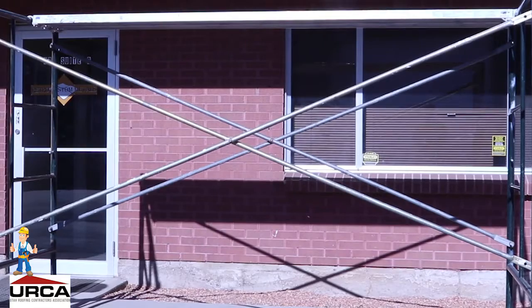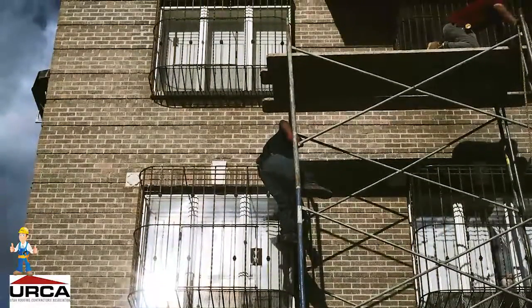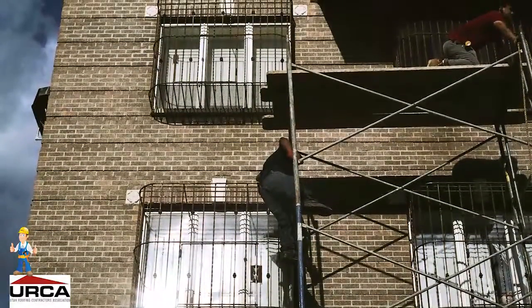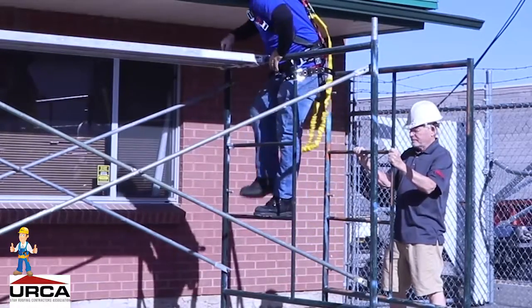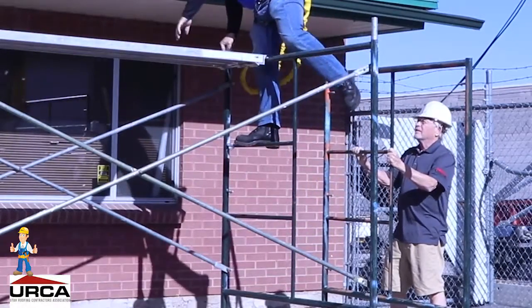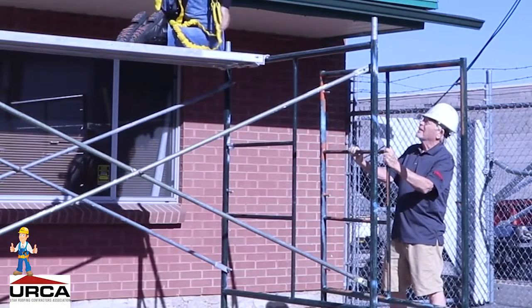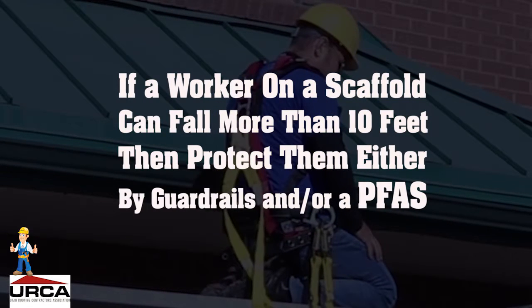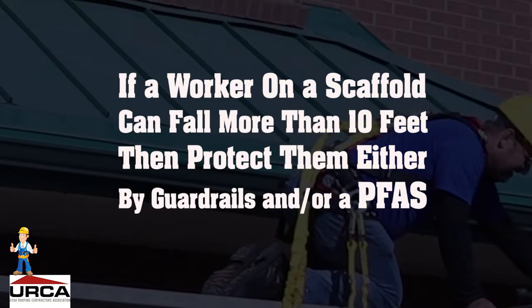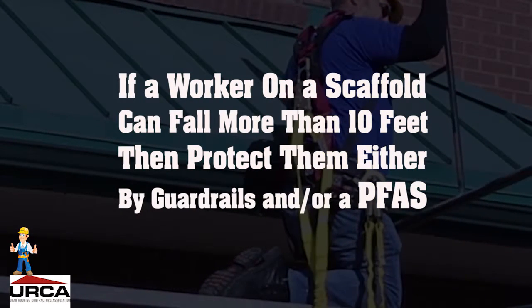Never access a scaffold by climbing on the cross bracing. Always provide a safe way for the workers to get on and off the scaffold without climbing on the cross braces. PFAS must be used on any scaffold 10 feet or higher above any level, and the PFAS must meet OSHA standards. Basic rule is if a worker on a scaffold can fall more than 10 feet, then protect them either by guardrails and/or a PFAS.